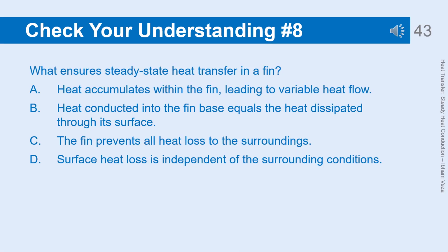The answer is answer B. Heat conducted into the fin base equals the heat dissipated through its surface. Explanation of incorrect answers. A. Incorrect. In steady-state conditions, there is no heat accumulation. Heat flow is constant throughout the fin.